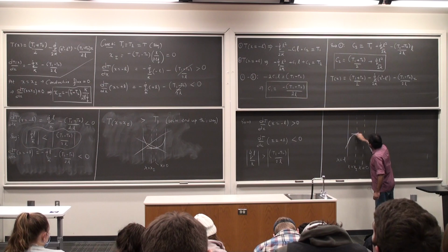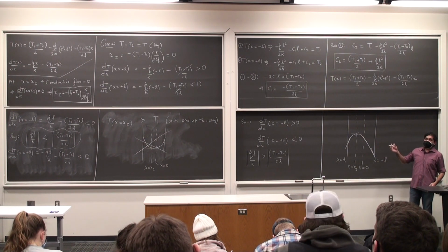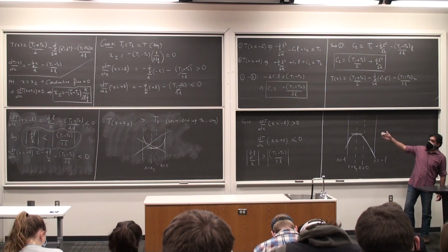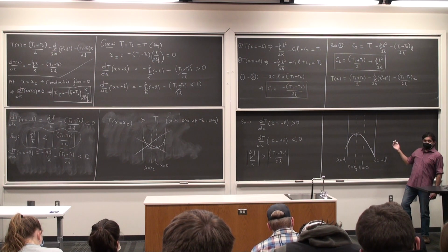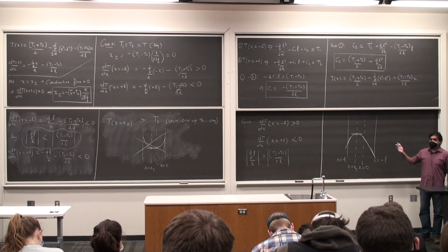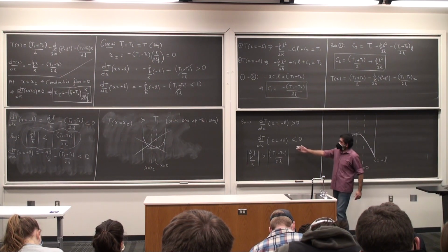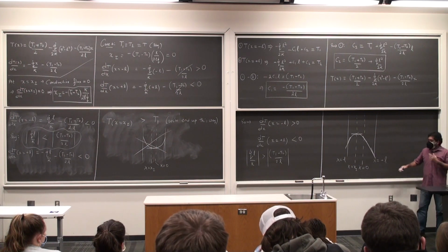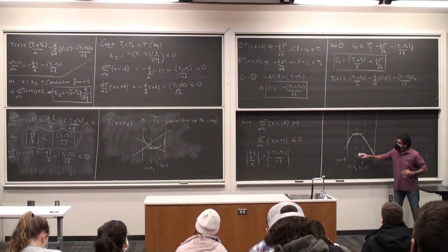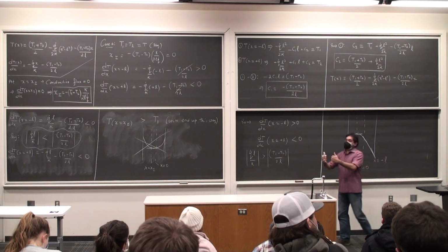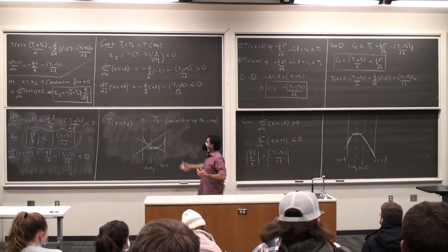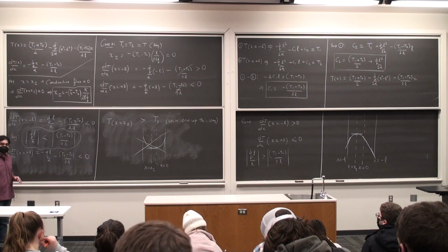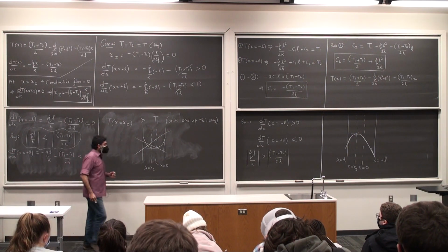And so this obeys all the constraints of the problem. T at x is equal to xi is going to be larger than T1 and T2. No changes on that. This criterion has to be met for this problem to physically have a profile of the following sort. If this x is equal to xi does not lie physically within the limits from 0 to minus L, then anything else can happen. Then I can have a situation that I have just described. Okay? I'm not going to go through the details of that. Maybe you'll have that as your homework problem next week.